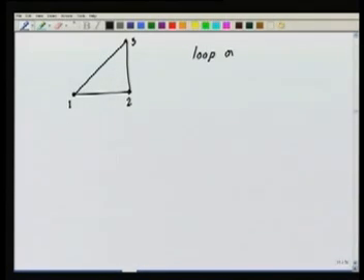So okay, I now have this side neighbor. So now let's say that I go to element 1. This is the local 1, this is the local 2, this is the local 3. Now this element 1, I start looping over the edges, loop over the 3 sides of the element, and I check if that side has a negative neighbor. Okay, if it has a negative neighbor, I check whether that negative neighbor is minus 4.